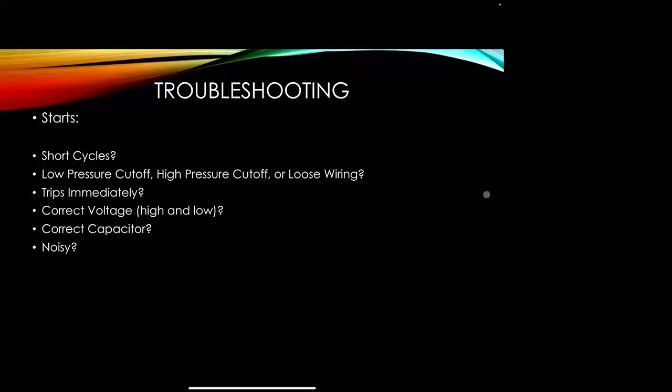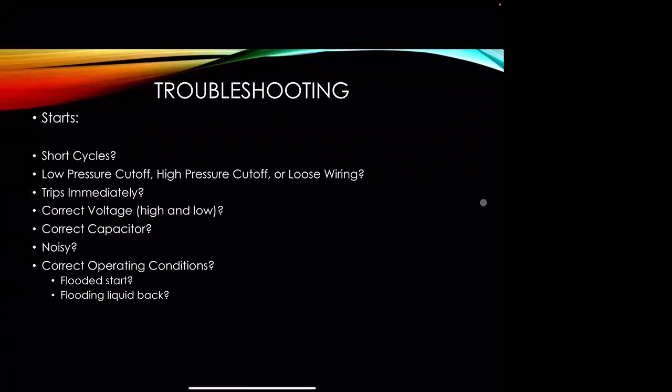Is it noisy? What's it sound like? Is it the correct operating conditions? Is it 30 degrees outside and we're having some noise issues here? It could happen. Do we have a flooded start or flooded liquid back to the system, to the compressor?